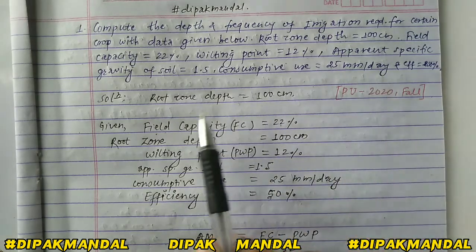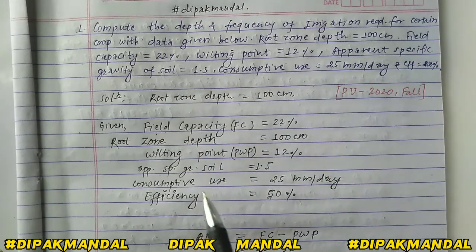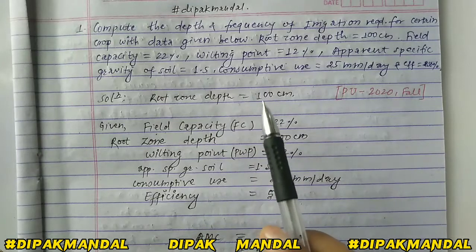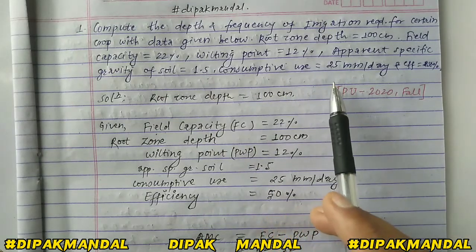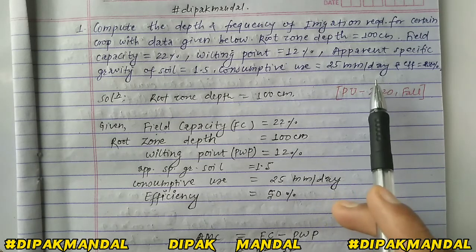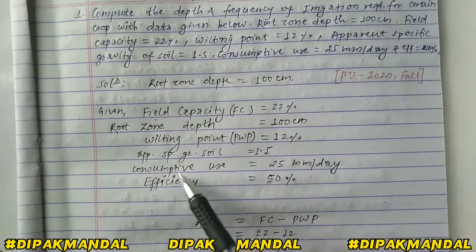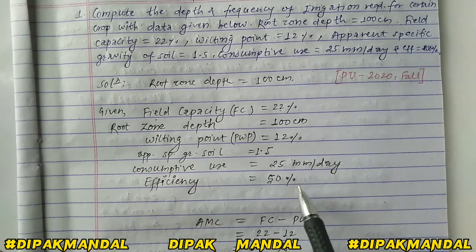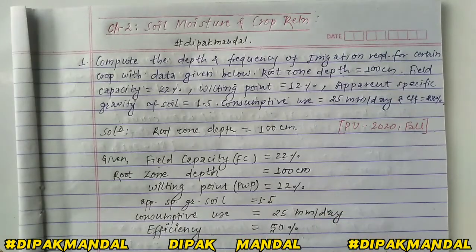Apparent specific gravity of soil equal to 1.5, and the specific gravity of soil is given over here as 1.5, and consumptive use equal to 25 mm per day. Okay, so here consumptive use is equal to 25 mm per day, and efficiency equal to 50%. Okay, so this is the data given. Now we have to determine the depth and the frequency of irrigation.